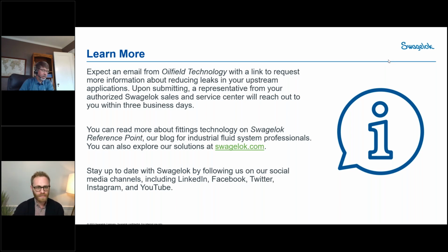Yeah, so that's an interesting question. So there's some assumptions with that type of sealing technology, that tapered design. If you remember, there was a Teflon tape that is put onto that thread. And the assumption with that corrosion green dot is that that tape is properly put onto the thread, so it's down to the bottom and up to the neck. So that seal is made that entire length. So there's no place for any corrosive material to get inside of that sealing distance and remain stagnant.